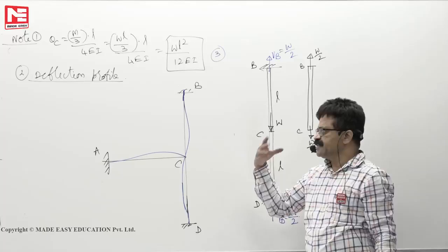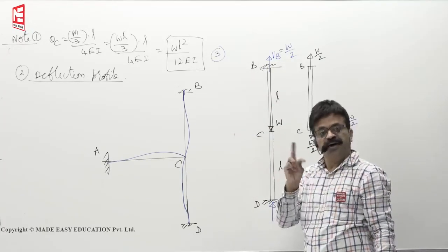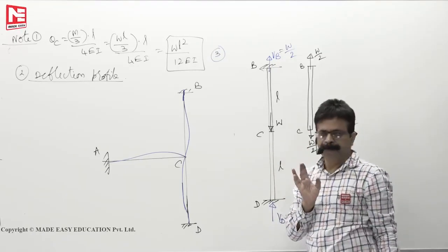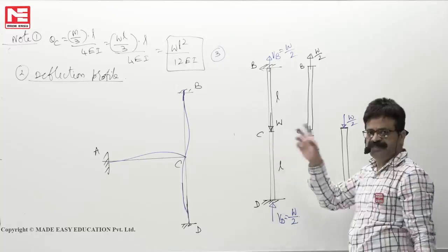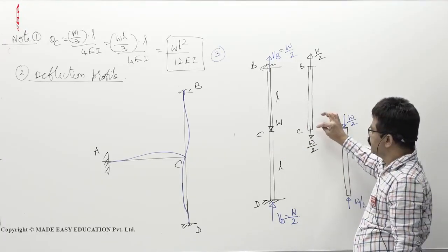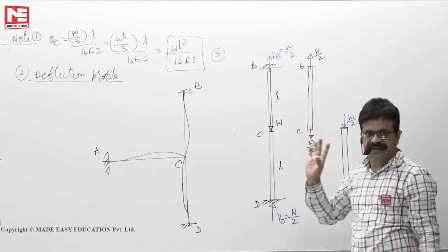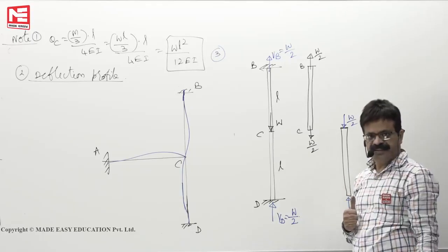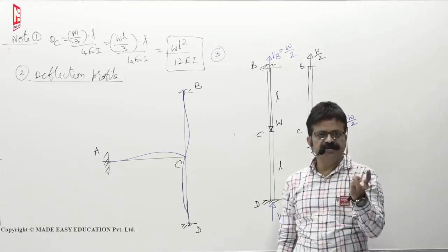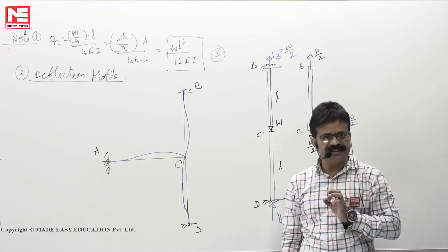Whether it is strength of materials or structures, applied load is there, so then it will be shared. How they will share depends on either axial stiffness or flexural stiffness. This is your strength of materials first chapter problems we have done like this. But here the elongations, contractions are neglected in the moment distribution method. Okay, so that is an assumption. Axial deformations, shear deformations are neglected in moment distribution method.